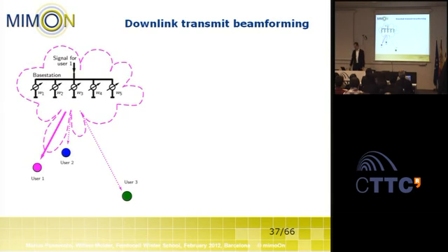So I want to consider now a downlink, for example, in a femtocell. Let's say I have a femtocell equipped with several antennas, and I want to serve my femtocell users first. So for each user, I can freely design a beamformer. So basically, I take the stream for the users, and I now adjust the different complex beamforming weights of the antennas to create a beam pattern that is indicating the signal strength towards a particular spatial direction.